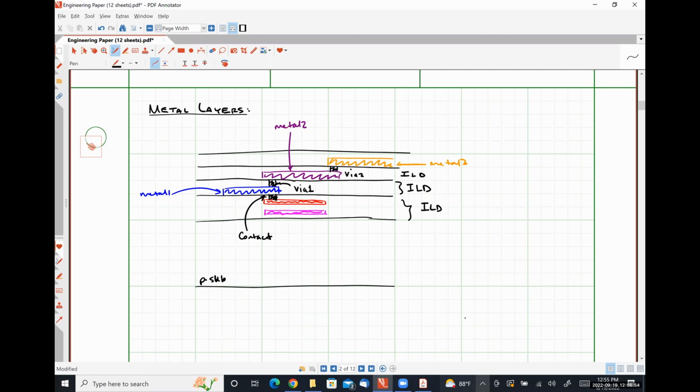A bonding pad is a macroscopic structure on these microscopic chips, okay? It's relatively large, okay? So a bonding pad has minimum dimensions of 72 microns by 72 microns, large enough to bond a small wire to that particular point on the circuit. That's why it's called a bonding pad. We literally use robots to solder wires to these very, very small pads, okay?